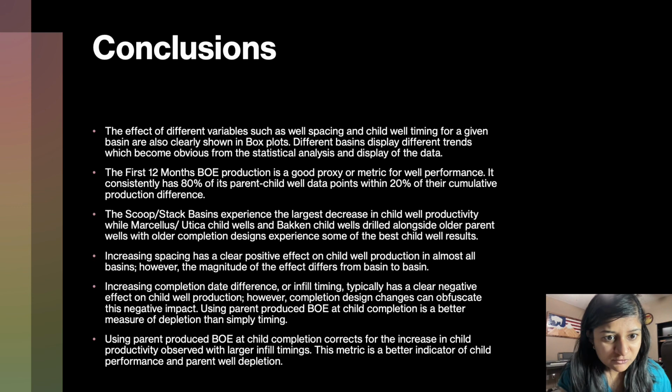Increasing completion date difference or infill timing typically has a clear negative effect on child well production, but completion design changes can obfuscate this negative impact. Using a parent-produced BOE at child completion is a better measure for depletion than simply timing. Using a parent-produced BOE at child completion corrects for the increase in child productivity observed with larger infill timings. This metric is a better indicator for child performance and parent well depletion. That is the conclusion of this presentation or this paper summary.